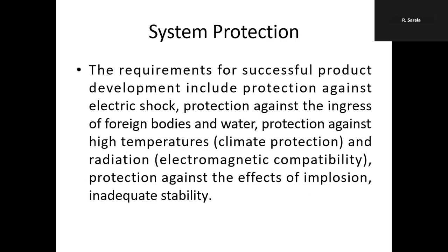So the requirements for successful product development include protection against electric shock, protection against the ingress of foreign bodies and water, protection against high temperatures, climatic protection, and radiation, electromagnetic compatibility, protection against the effects of implosion, and inadequate stability.